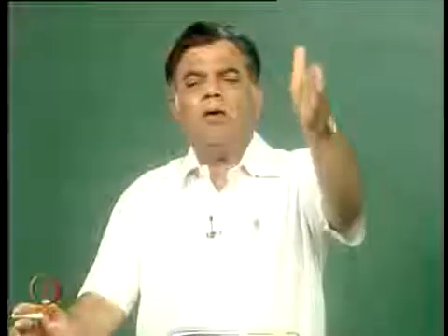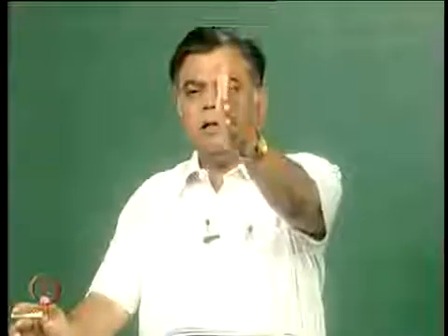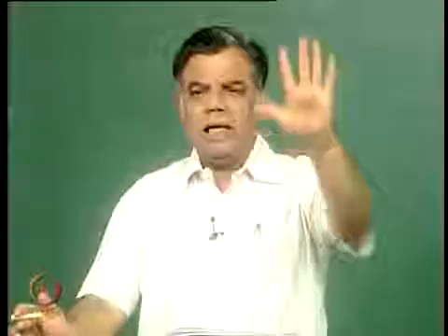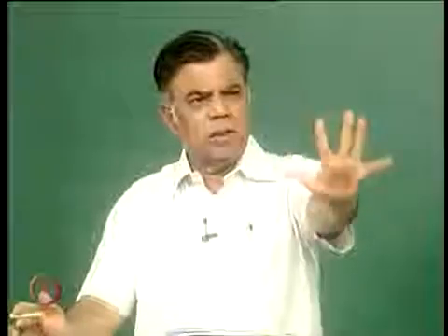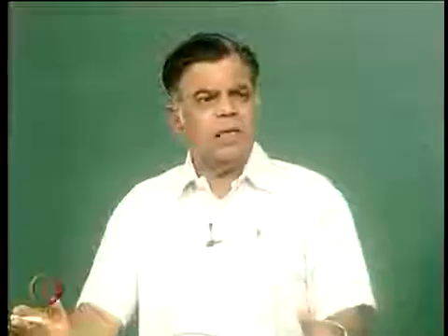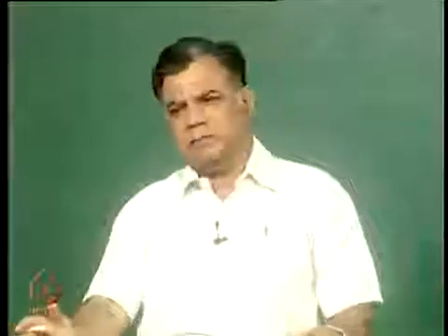So now look at the expression, the energy equation, the entire set. Now all of them are actually ordinary differential equations. This is point number 1 you should notice, observe, appreciate. A complete set of nonlinear partial differential equations, in this particular physical model we have taken, with certain fairly reasonable, acceptable, justifiable assumptions, is brought down to the simplest. We cannot get anything simpler than this in convection.